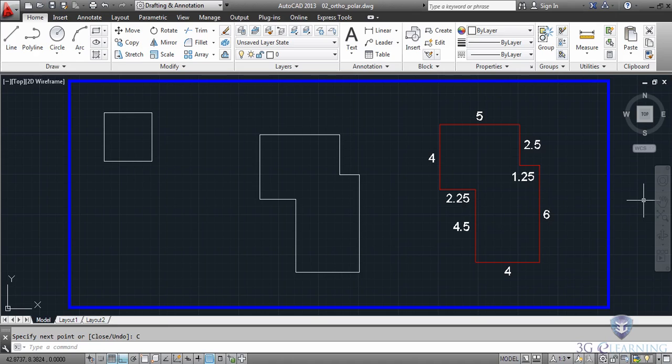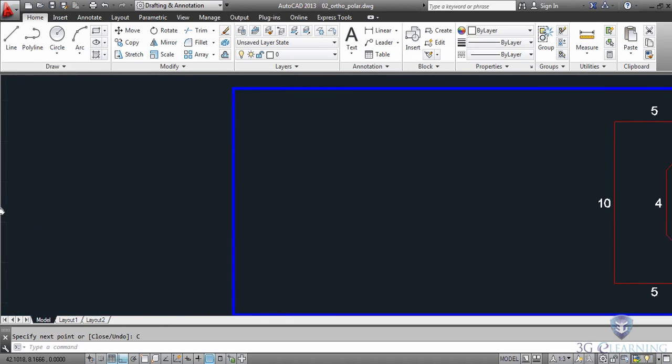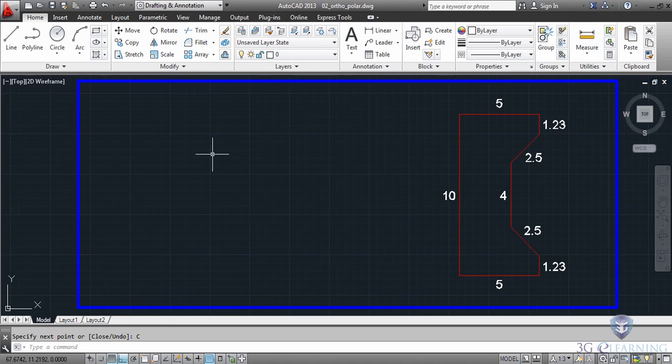Now, what if you'd like to snap to additional angles? Well, that's what the polar setting is for. Let's take a look. I'm going to pan my geometry over. I'll launch the line command again and pick a point on screen. You can see that the ortho is still locked. I'm going to come down and click the icon right next to ortho. This guy stands for polar tracking. Note that we can also toggle this tool using the F10 key.